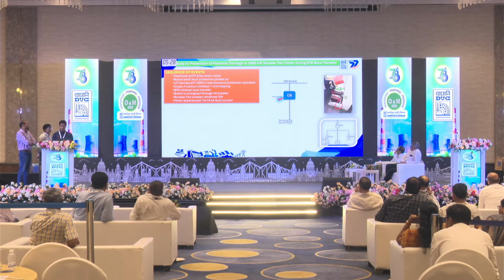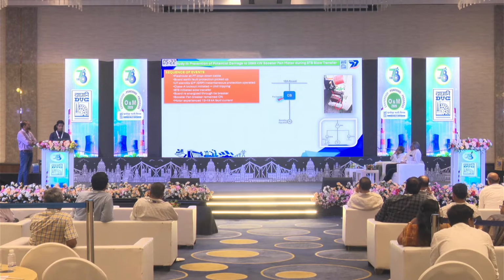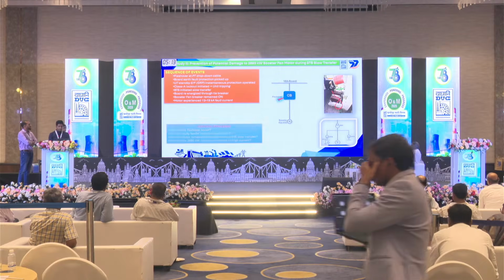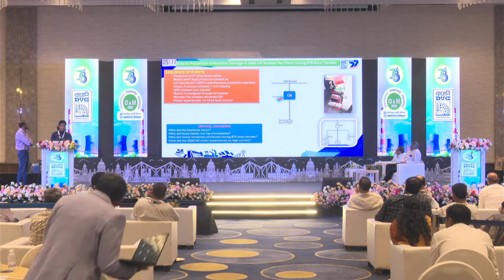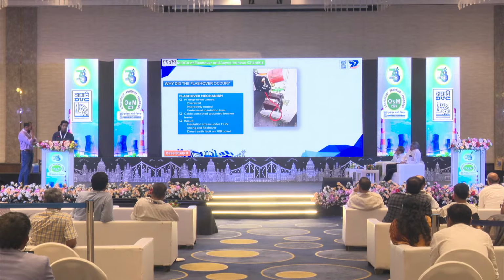Class A protection. So BTS initiates slow transfer, and during that process, the booster fan motor experienced 19 kiloamps of fault current in its B phase. In that case, we were lucky enough that the motor did not get damaged while withstanding this much current. This raises several critical concerns. We do root cause analysis of all the concerns.